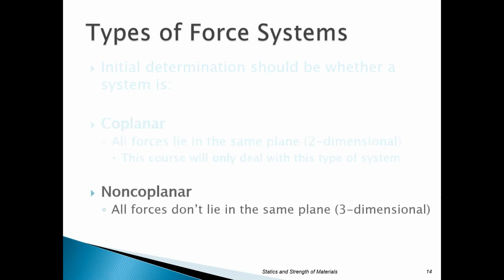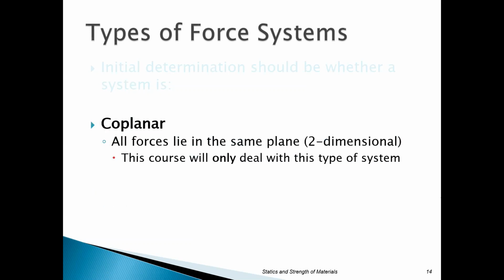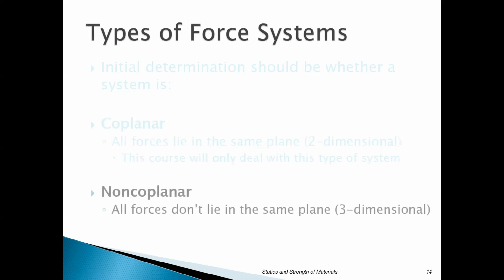If we get to the non-coplanar, what you're saying is not all your forces lie in the same plane, three-dimensional. And what that gets into is multiple equations. So you will see with the coplanar, you're basically dealing with 3 equations. When we get into non-coplanar, it would be 6 sets of equations. Okay, so we're not going to be doing anything from a non-coplanar standpoint. So that's the good news.